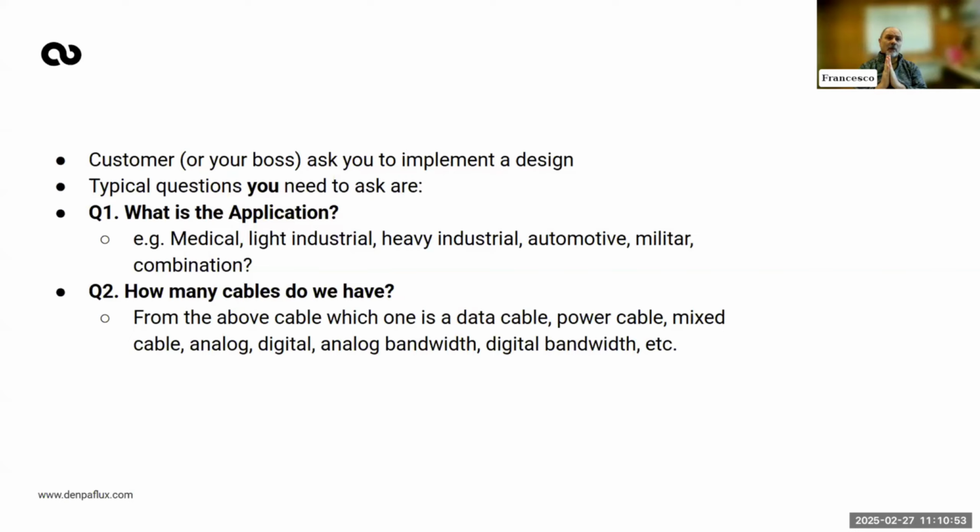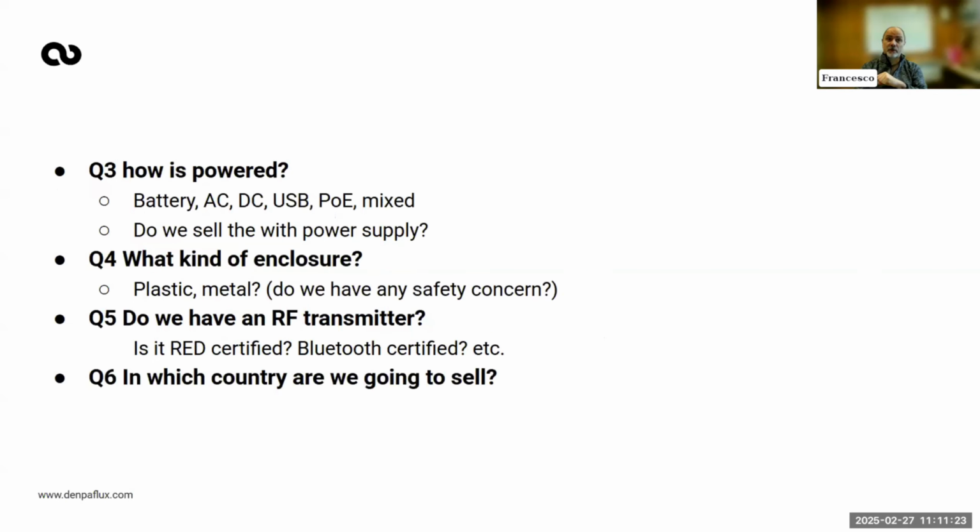So a question you need to ask is, if you have some cable, how long is this cable and where does it connect to? Okay, and check with the standard to understand if you need to do some specific test on this cable. Typical tests are surge and fast transients. Of course, you have other tests you have to do, like conductive emission, but usually the most severe is the surge.